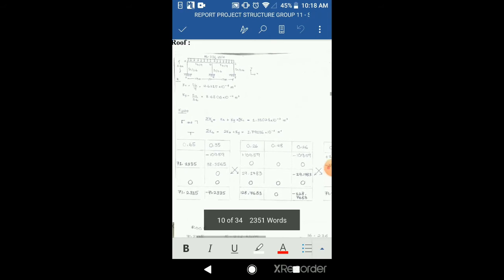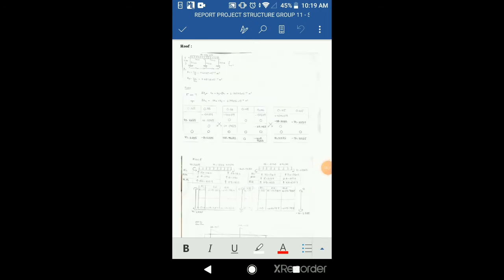So we calculate the total stiffness at the joint, which, for the L shape, the total stiffness at point A and point C, we just add the horizontal stiffness and the vertical stiffness. Meanwhile, for the total stiffness at point B, we sum up the two stiffnesses AB, BC, and one vertical stiffness member, which is BE.